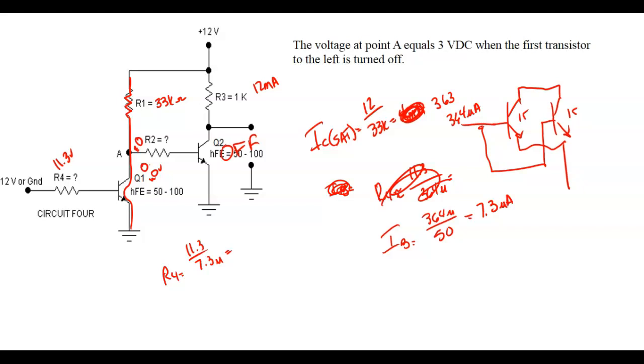But how can they bring that to the outside world? Well, they bring it out to the outside world through a bipolar transistor. Through an optical coupler. So normally we have an optical coupler on the programming controller, and then over here we have a photodiode or phototransistor.